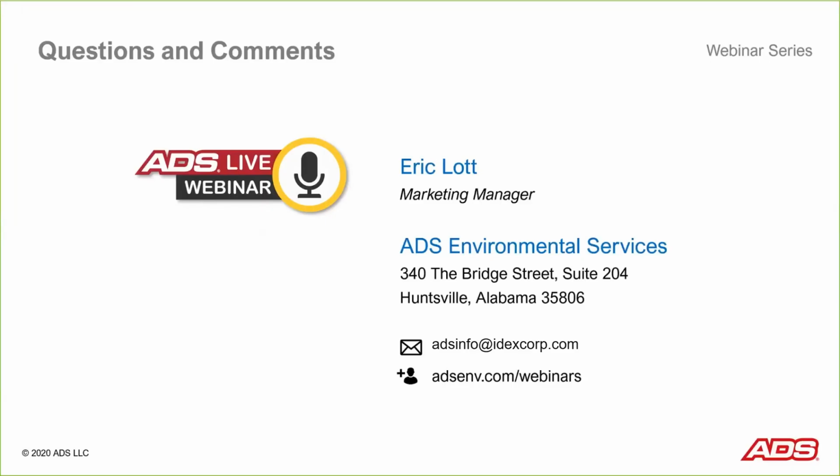Okay, so that's for some of our international webinar participants. In some parts of the world, the Manning equation is not used to design sewer systems. They prefer to use and are required to use something called the Colebrook-White equation. And it essentially does the same thing. So yes, it can certainly be used instead of the Manning equation. Its parameters are a little bit different, and it's a little bit more complex to handle mathematically, but it can be used in the same role on a scatter graph as the Manning equation. So the answer is yes.